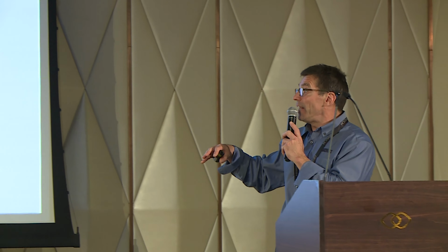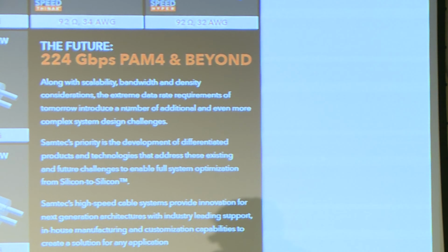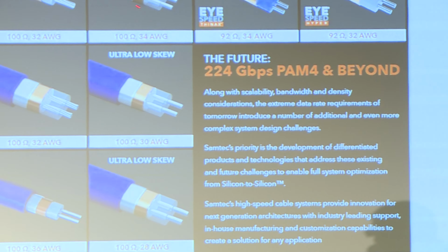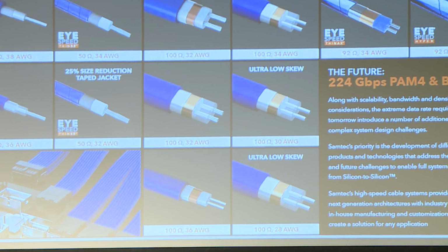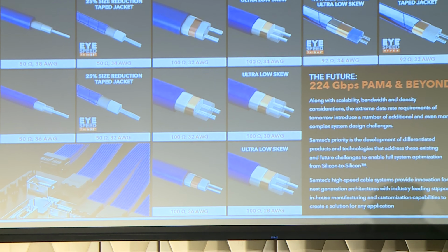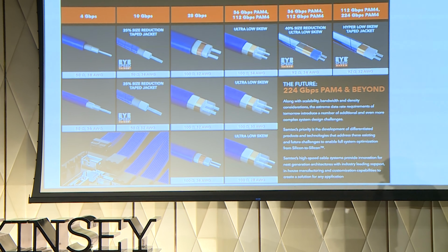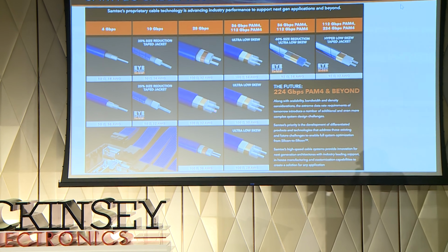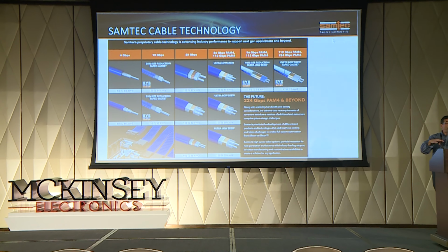And this now shows us the heart of what's in these cable technology. So for the main purpose here, they're all based on a twin-ax design of 2 conductors in a dielectric with a twin shield and a jacket. Depending on the iteration of cable, we've gone from stranded cores to solid copper conductors, which improves the SI performance, doesn't affect the bending too much.